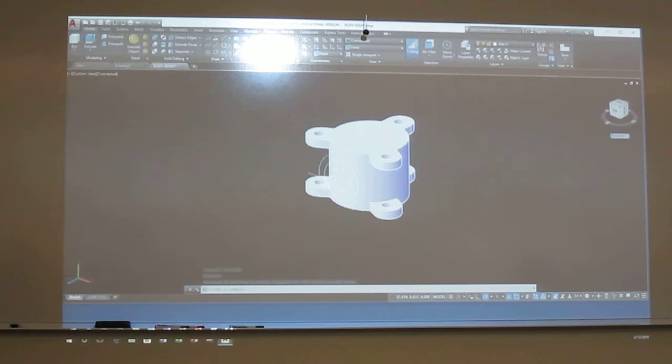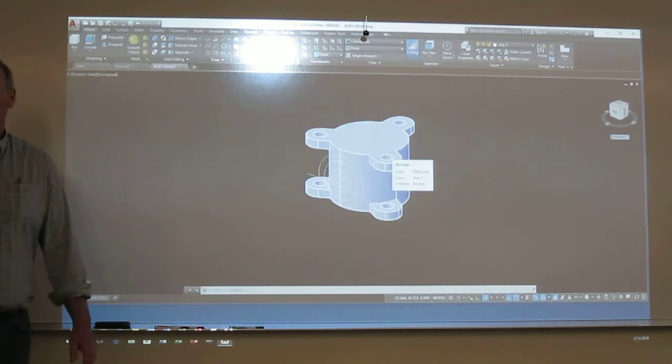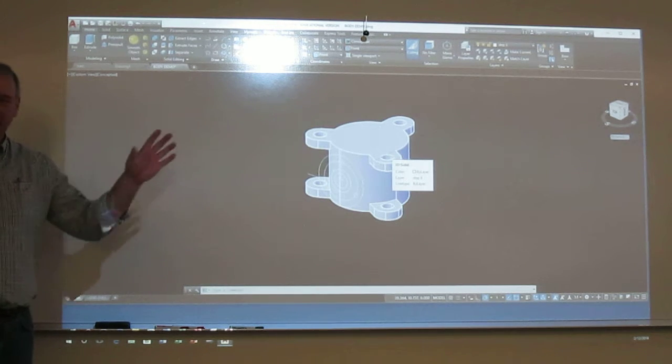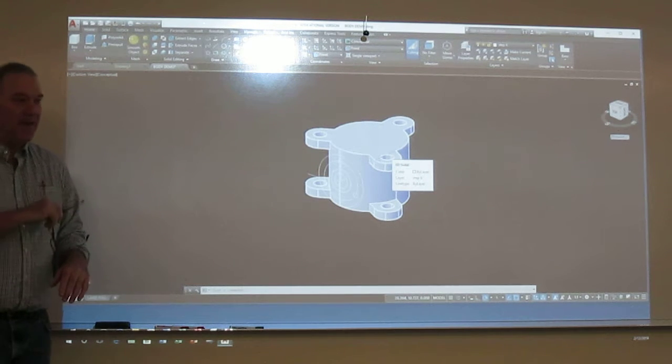Now I'm going to switch to this front and deal with it. Generally do your positives first, negatives second. Okay. So, one thing you might do here, folks, I know one thing when I'm coming out and helping you folks is you're not taking advantage of layers. You can create as many layers as you want. Freeze, thaw stuff that gets in your way.